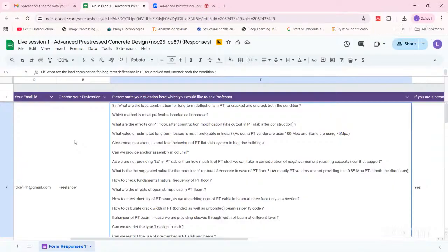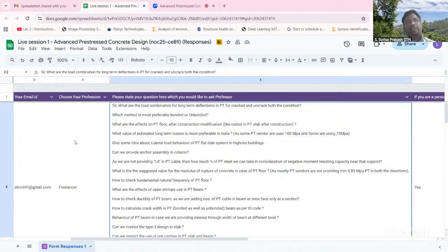Of course, you don't want to have too much pre-stress either, because then your cost will go up and you'll have excessive camber, and placing the tiles and all will become difficult. But having said that, 1.25 is a really good number that we should shoot for.